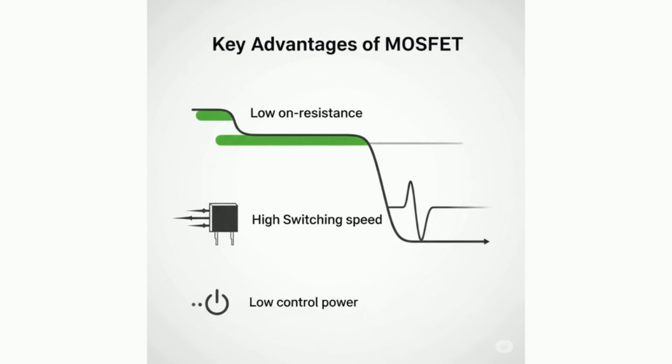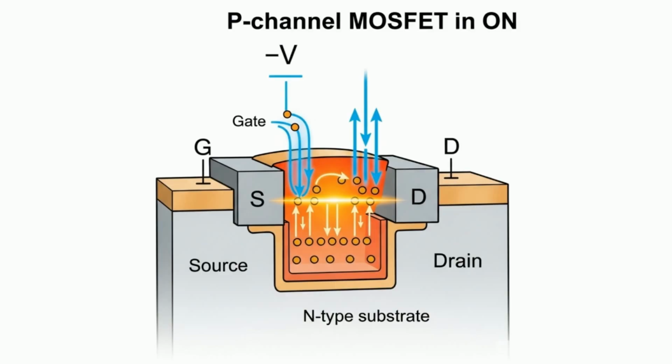With miniaturization came challenges. Leakage currents increased. Short channel effects made precise control more difficult. Heat dissipation became a growing concern. To address this, engineers developed advanced structures like FinFETs, 3D MOSFETs with vertical channels, and explored new materials like high-K dielectrics and metal gates to replace traditional silicon dioxide and polysilicon.